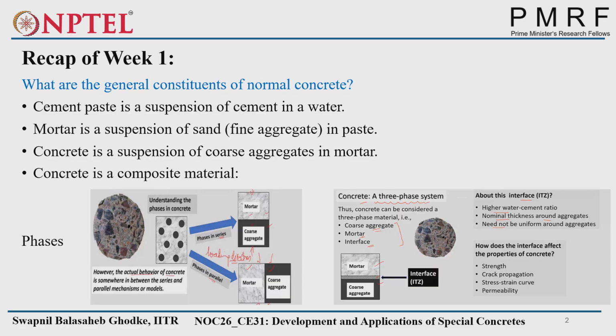And another way is based upon the mix proportion, that is the lower water to cement ratio. Can anyone tell me, if we have the water cement ratio 0.5 and if we have the water cement ratio 0.3, still we will say the 0.3 water cement ratio gives high strength. Why does it happen? Because water is required for the hydration, right? Yeah, please tell me.